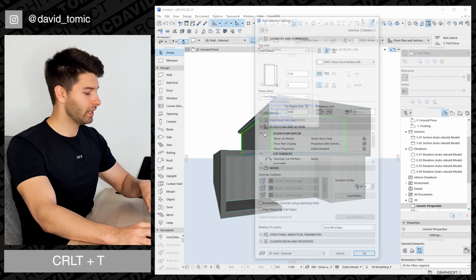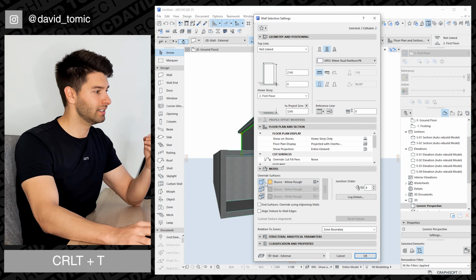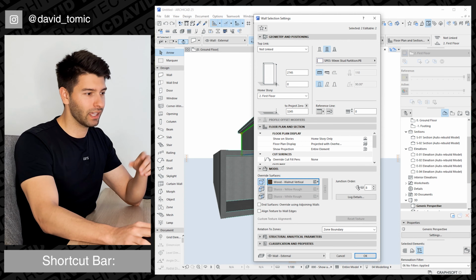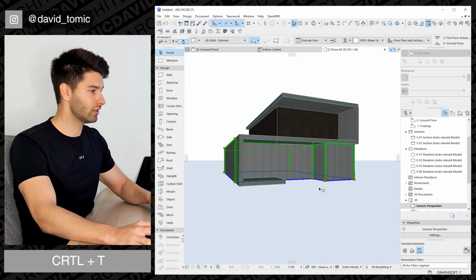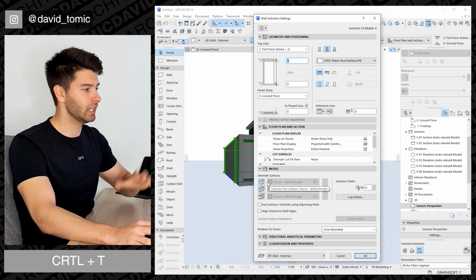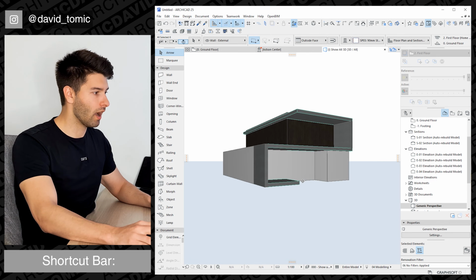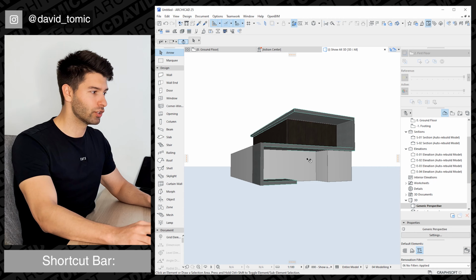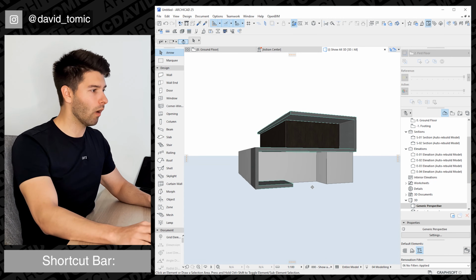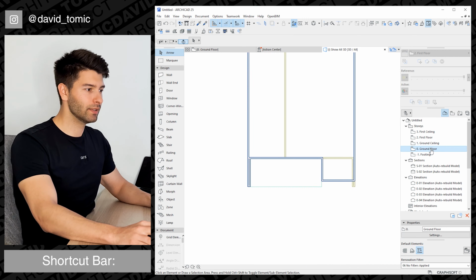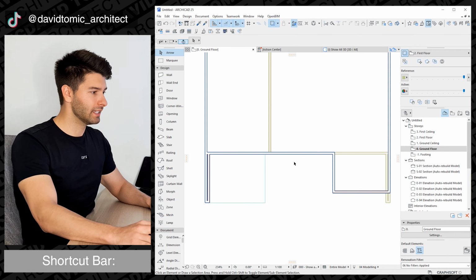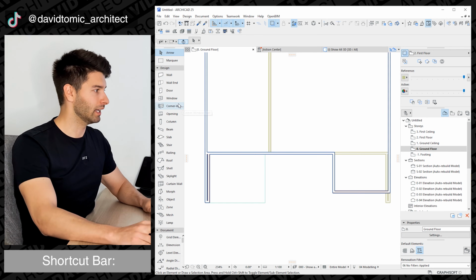Now these two walls up here, I want them to be in a nice dark timber. So let's make them a vertical walnut and finish that off. The remainder of the house, by pressing Alt G, I'm going to paint all that titanium white. So it's a nice harsh contrast between the concrete and the white render, and we have our dark wood up here as well. Now let's come into our ground floor and start adding some openings and some elevations.